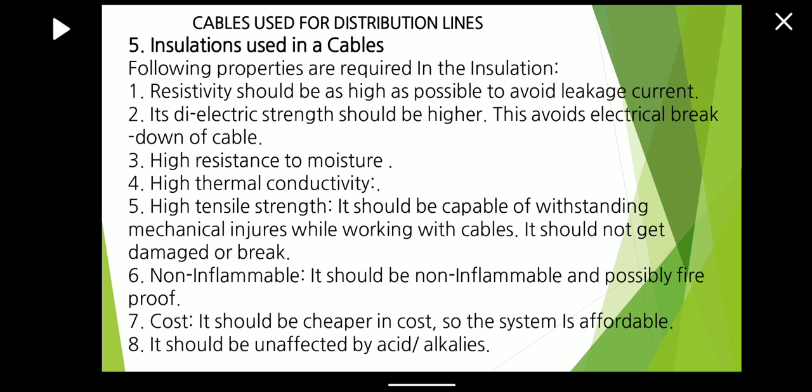Second is its dielectric strength. Dielectric strength should be high, and this avoids the electrical breakdown of the cable. Then next is high resistance to moisture. That is, it should be non-hygroscopic so that it does not absorb moisture.